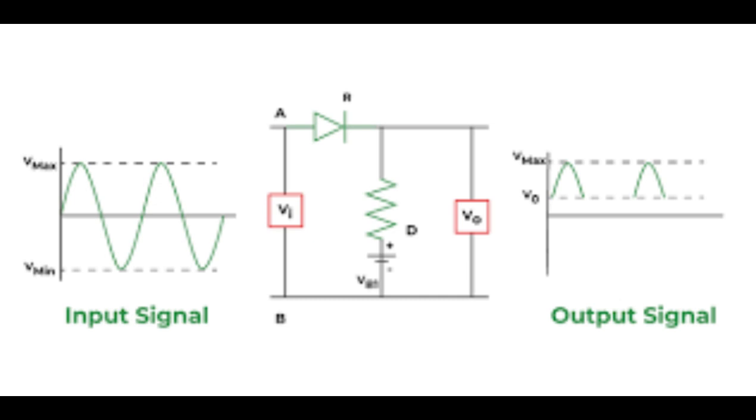I will explain the function of a clipper circuit. A clipper circuit, also known as a limiter or amplitude selector, is an electronic circuit designed to prevent an output signal from exceeding a predetermined voltage level without distorting the remaining part of the waveform. Essentially, it clips off or removes portions of an input signal's waveform that lie above or below a specific reference. Clipper circuits modify waveforms by effectively flattening the peaks of the signal that exceed the set clipping threshold.